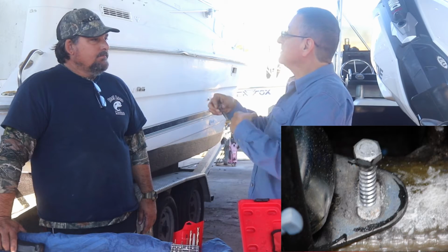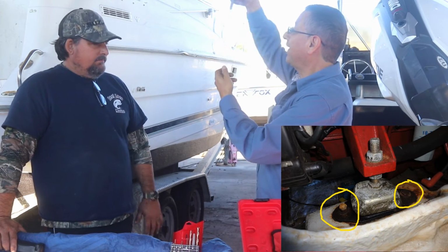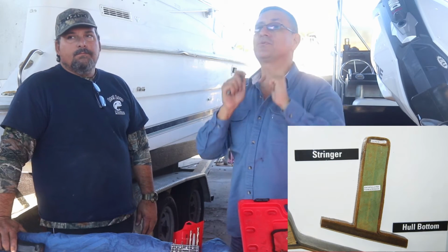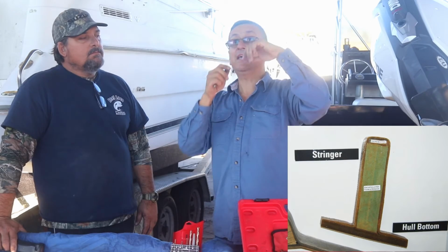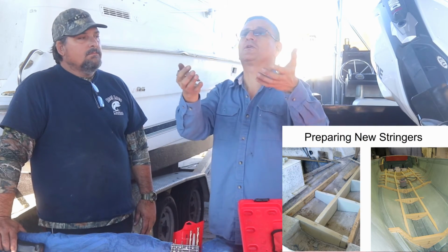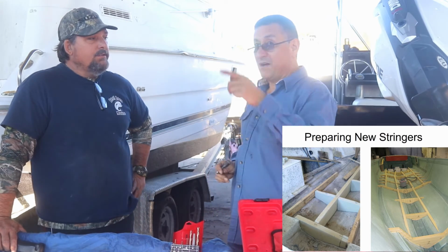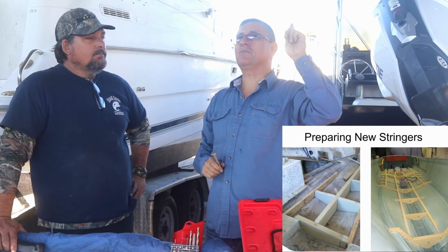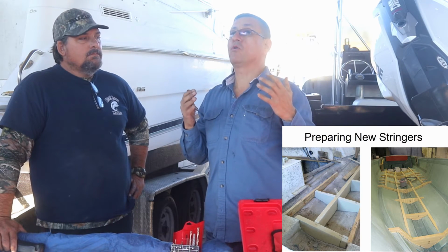You know when the stringers are damaged, what happens with this bolt? It'll pull right out, it'll twist. Because internally the stringer is hollow, because it absorbed humidity and the foam is gone. We are going to repair a stringer. We are going to replace stringers in our class of composite materials. Yeah, we'll be learning how to make stringers. And we are going to replace the worst-scenario stringer with foam internally, with wood or with metal.